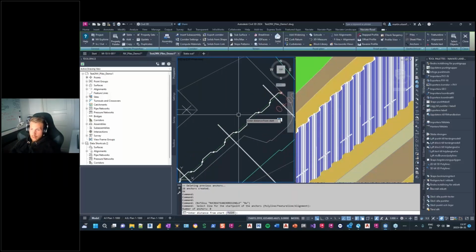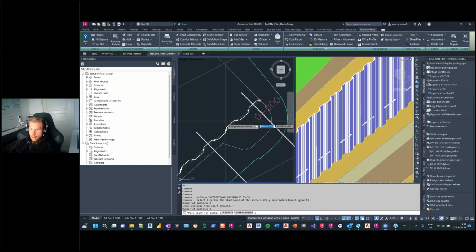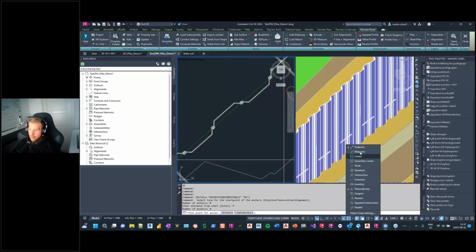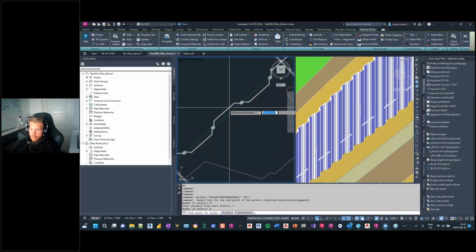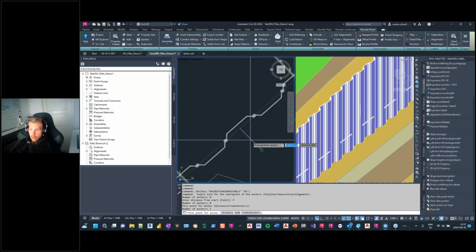And then I can give a station number where I want to put them, or I can use this alternative that is called point, and then I can just point graphically where I want my extra anchors. So activate the midpoint snap, so I will be able to snap in the middle of the sheet pile. I just press there. And now when I have put out my first, I can see I got this other alternative in the command line.